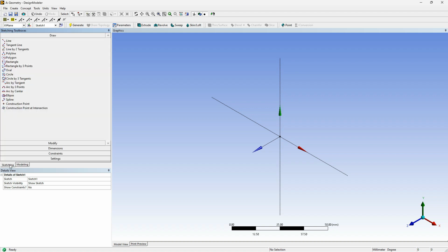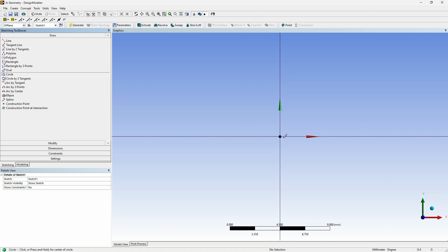Since you want to work with the circle dimension, you can click on Z to make it horizontal enough for us to see our design, then click on circle, zoom it out. Since you're working with small shapes, you don't want something big. Ensure it shows P before you click, and then just drag it out a bit.